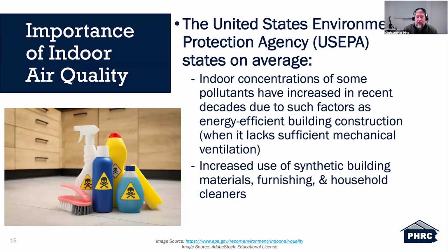It's a proven statistic that increasing the energy efficiency, the tighter you make it, is the most cost effective way to do that, right? But you just can't do half of the equation. There is always a reaction, right? When you tighten up that building, when you condition that space and you want to keep it in the conditioned area, therefore you tighten up the enclosure, there's a reaction to that. And that is, well, now you need to get fresh air in. And that's where mechanical ventilation comes into play. When it lacks sufficient mechanical ventilation, it does increase the potential for pollutants. So we have to address that, and I will get into that a little bit later on.